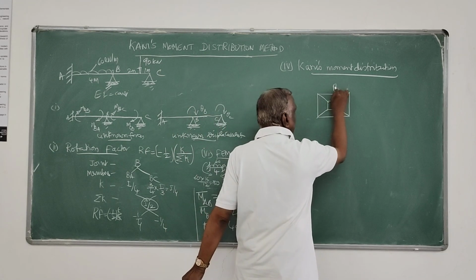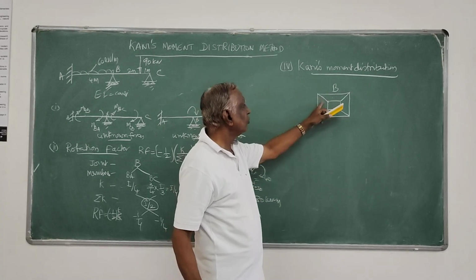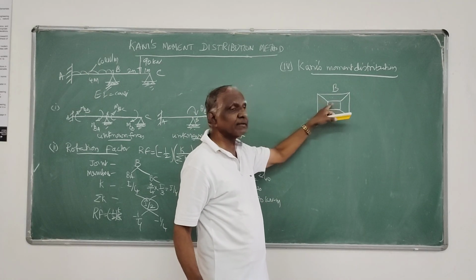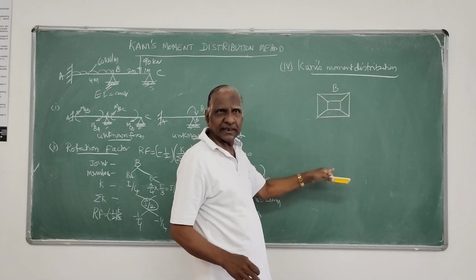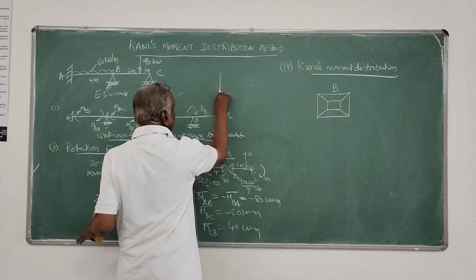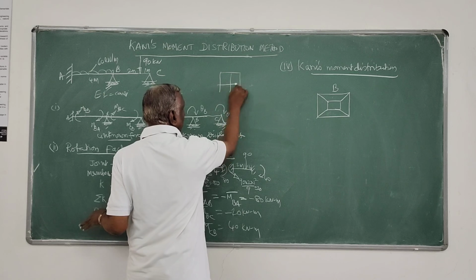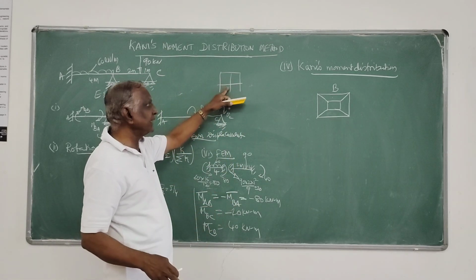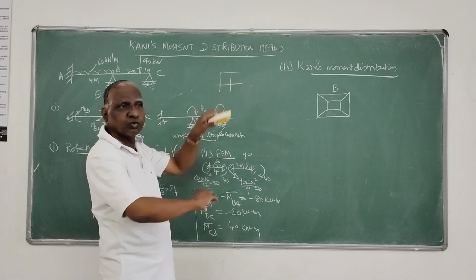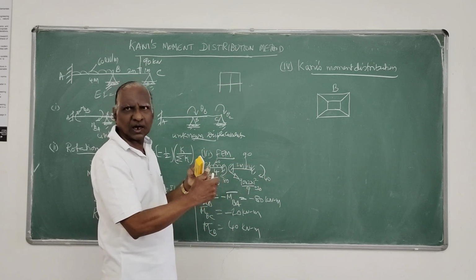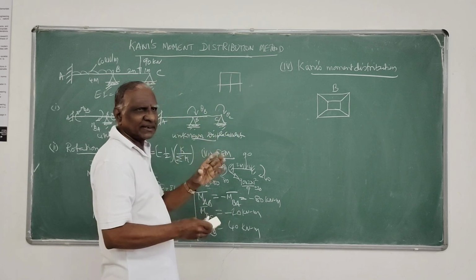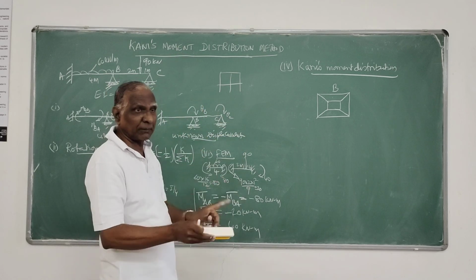This is joint B with four compartments in the space in between them. Why we are taking four, I showed you in the first example in our multi-story. At any joint in an orthogonal frame, you can expect four members meeting orthogonally. More than four you cannot get. That is left, right, top, bottom, mutually perpendicular.